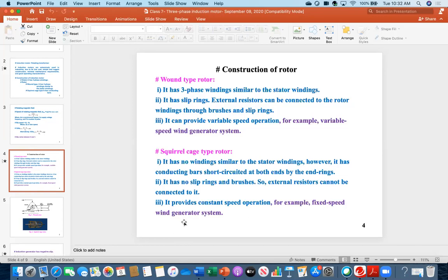speed is made fixed. So therefore, fixed speed wind generator means wind speed is not fixed, rotor shaft speed is fixed with the help of mechanical arrangement. In the variable speed case, both rotor shaft speed and wind speed are varying. This means the variable speed wind generator is adaptive, compatible, flexible with the variation of wind speed. Initially it accepts the varying wind speed, but in the fixed case, inside there is mechanical arrangement, gearbox, and pitch system that makes the shaft speed of the generator fixed. Therefore, when I am saying fixed speed, this is the generator part, not the wind speed. In variable speed, the shaft speed is varying, and it is compatible with the varying wind speed. That is the difference.